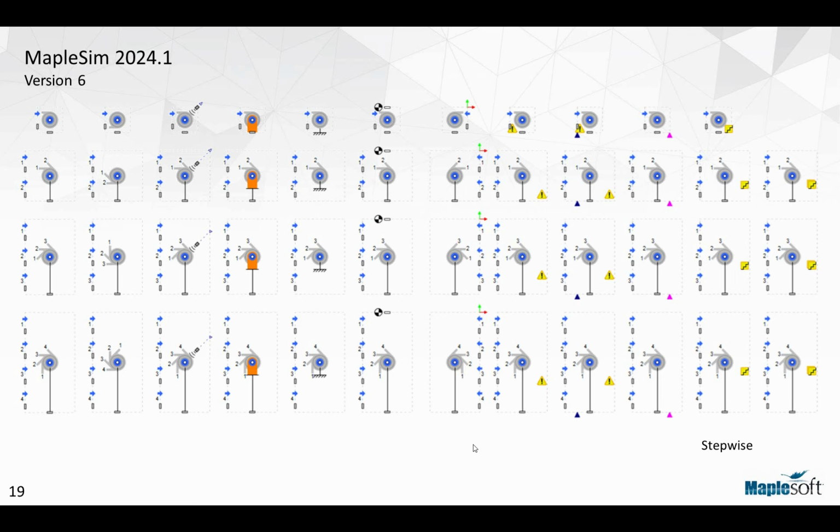And the multi-step comes from the fact that, let's say in the 2-web case, web 1, when it reaches the previous layer, has a step, and when it reaches the previous second layer, has a step. The same goes for web 2. So in total, for every revolution, you can have 4 steps. For a 3-web winding, you can have 9 steps, and for 4-web winding, you will have 16 individual steps. So let's take a look at examples.